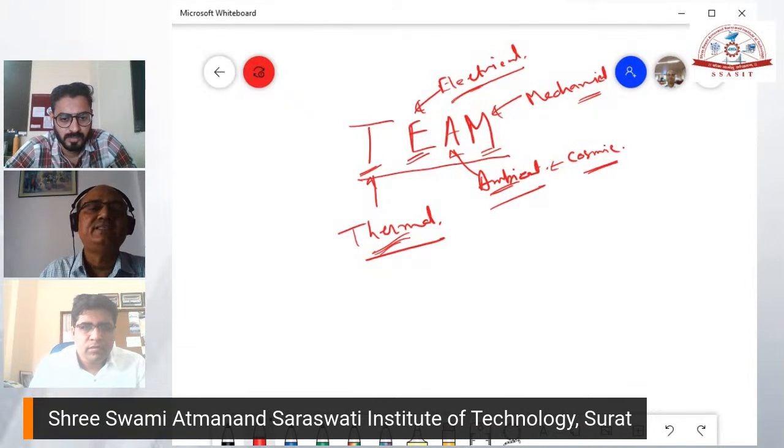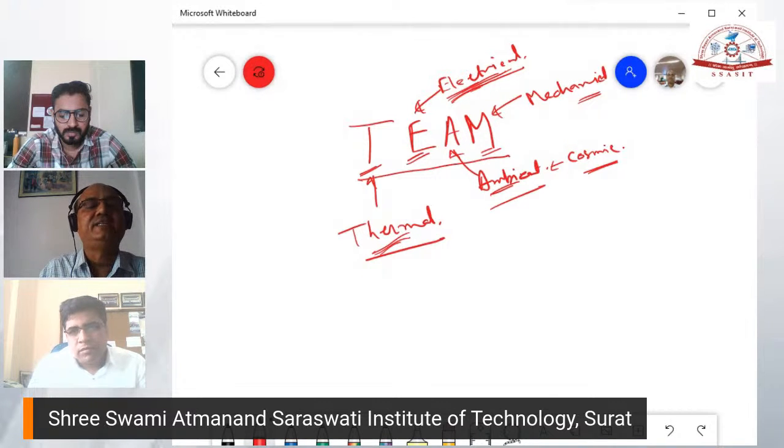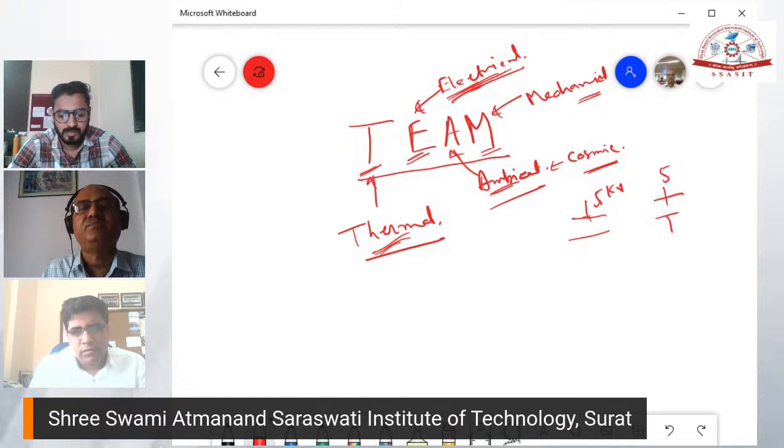Now, if the space charge is going to add electrical stresses, there will be an effect. You have to check how much electrical stress is added by the space charge. If one insulation is stressed by 5 kV and another by 5 volt, naturally you can understand the first will have more aging.